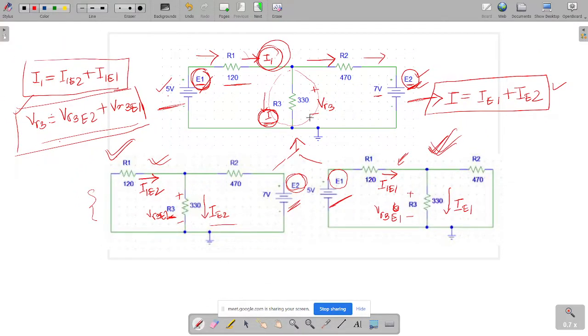So basically this is the particular circuit that we are going to solve today, and the method that we will apply in order to verify the superposition theorem is, firstly, we have to solve the circuit when both the voltage sources are simultaneously active. Then in the second step we have to deactivate one voltage source and solve the same circuit, and in the third step we repeat it by deactivating the other voltage source.